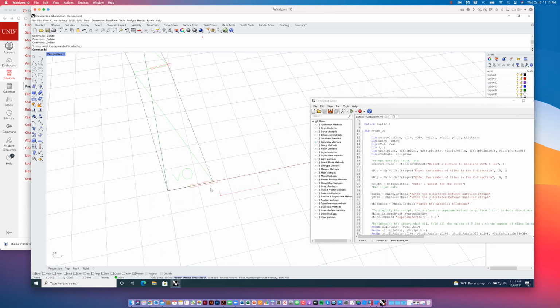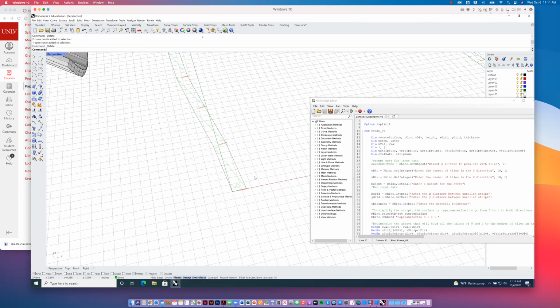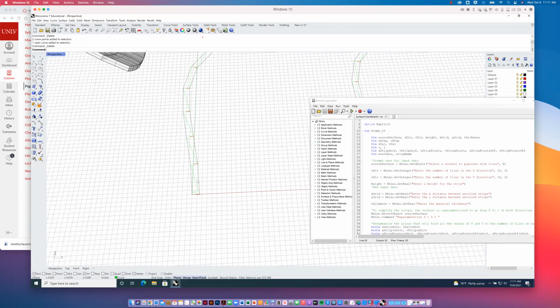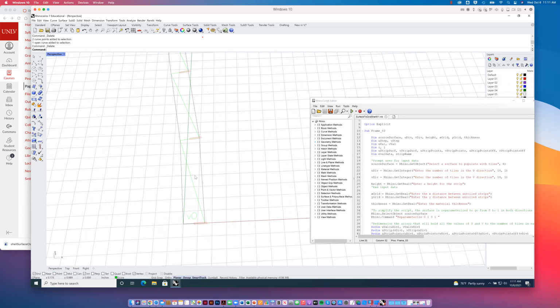Let's see here. For some reason I have the points instead of the curve selected. That's weird, right? I'm just going to go through and start to clean some things up for laser cutting. Another thing you might notice, and again, we can go back over this on Monday, is that these outlines are kind of exploded into individual polyline segments. So we'll probably join those together into closed polylines, to minimize the amount of jogging and traveling that the laser cutter has to do between cuts.